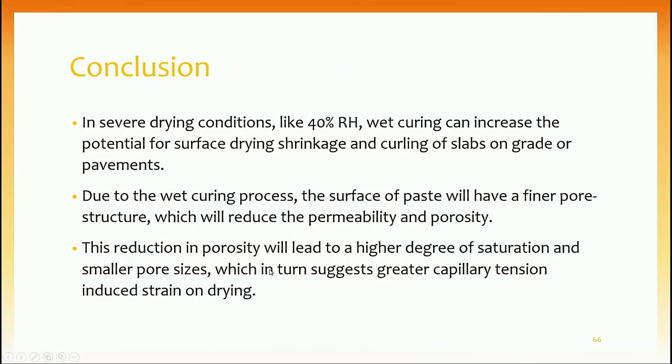Also, I'm going to summarize what I found in severe drying conditions like 40% relative humidity. Wet curing can increase the potential for surface drying shrinkage and curling of slabs on grade or pavement.